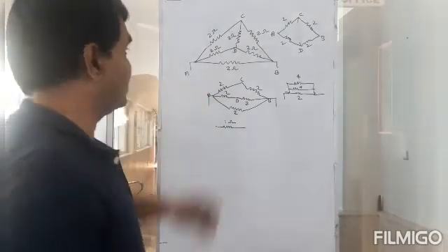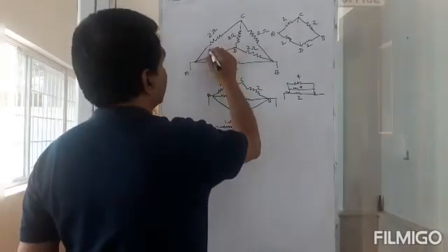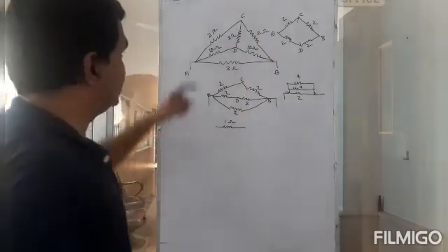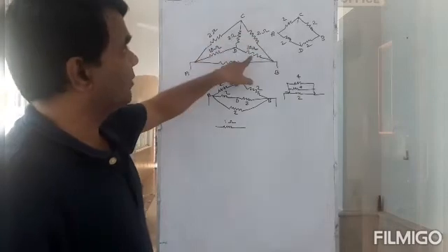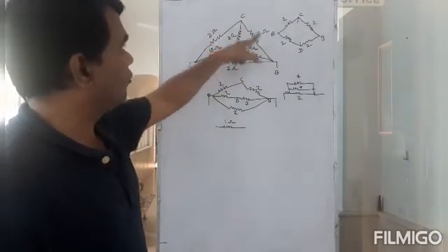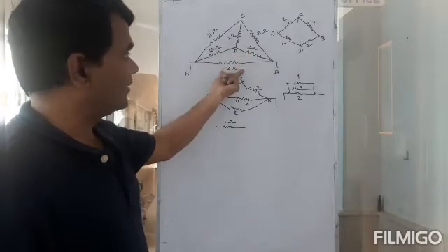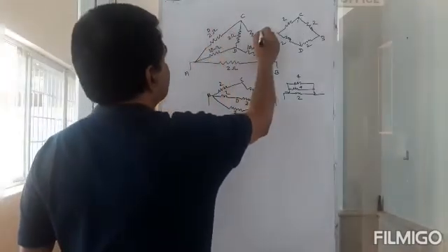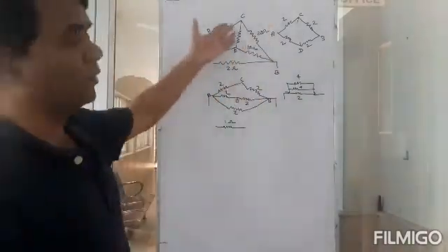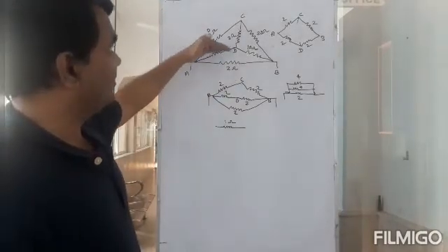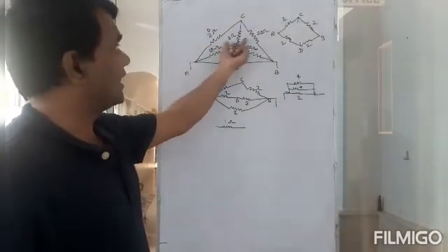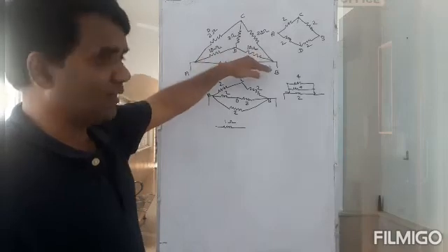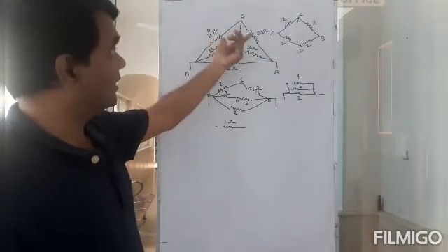Okay, it will work even if this is say 10 ohms and this is again 10 ohms. Then also you see R1 by R2 is equal to R3 by R4, so then also it will be gone. But then you will have 4 and then you will have 20 here and then 2 here. Or this can be 20 and this can be 20 also. Then also it will work, because 20 by 10 is equal, right? So then I can ignore this. Then it is simply 20 plus 20, 40, and 10 plus 10, 20, ignoring this completely. They are in parallel.